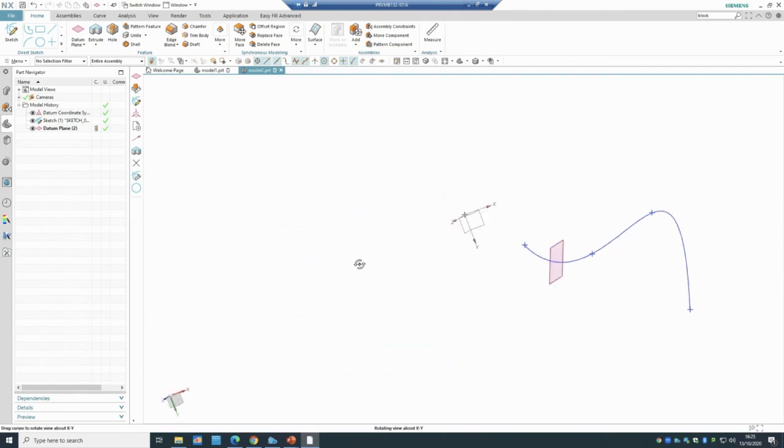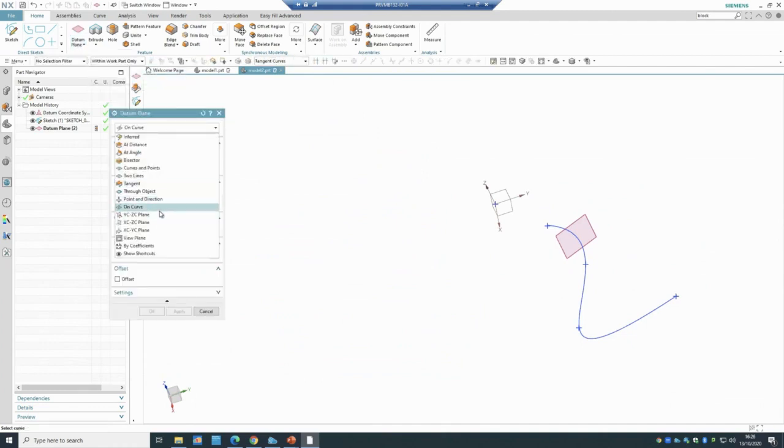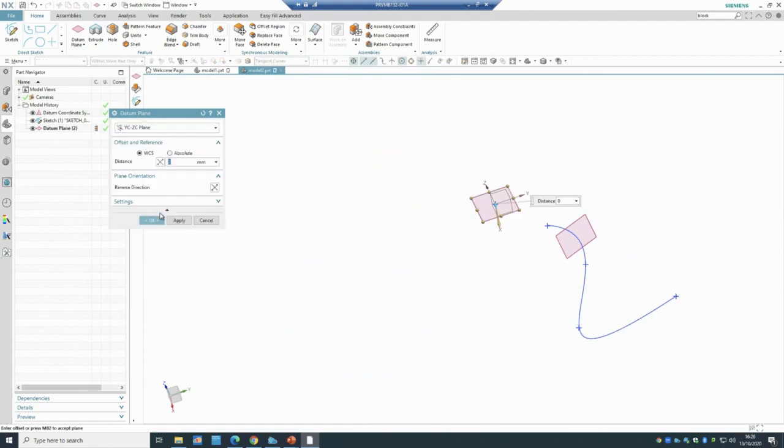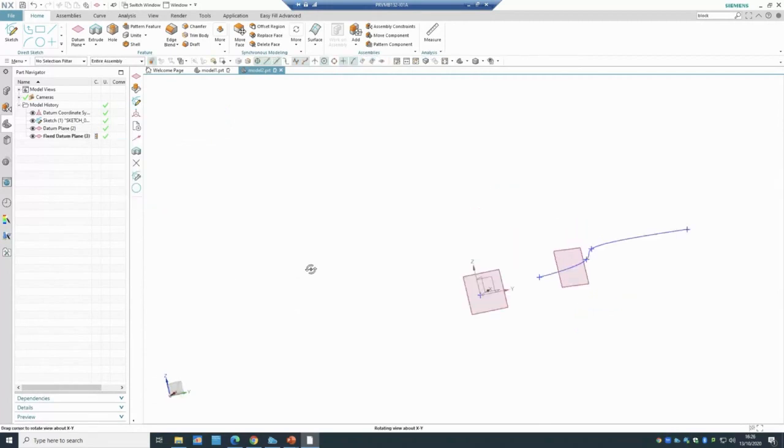The other things, there were 3 more options as well, and that's based on the planes that already existed. So XZ1, the YZ1, and XY1. So the 3 planes we have as a reference over there, you would be able to see it there. I would be able to use those as a reference. So I can just come here and I can say, yeah, I want to have the YZ plane, and it automatically finds the YZ plane for me. And I can even keep the distance as a 0, or I would be able to put a distance, for instance. You would be able to see that actually it's created a plane based on the YZ plane, which already existed.